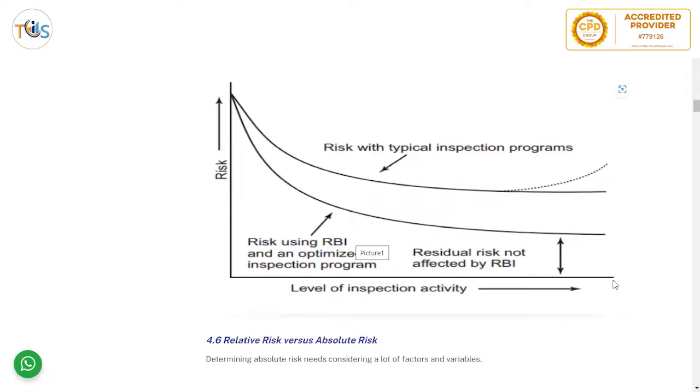So in the process, you might have polythionic acid corrosion, or due to increased moisture, you're actually disturbing the equipment too much. For example, with corrosion under insulation, if you want to completely remove all the insulation, you might actually create more damage because you have exposed the vessel and made it vulnerable by removing the insulation.